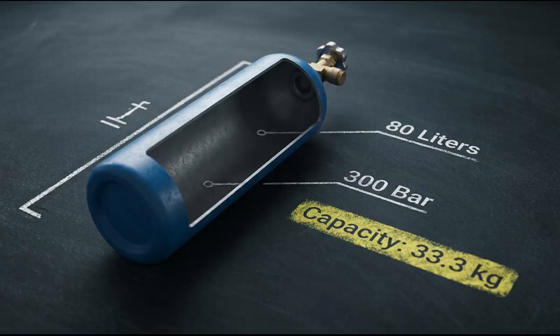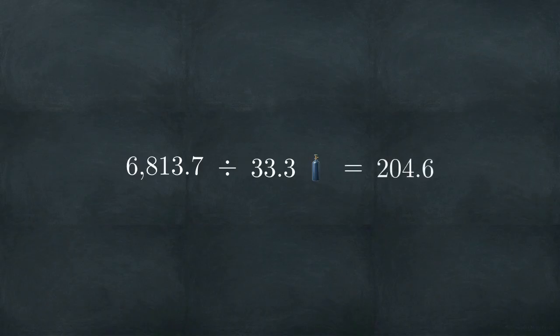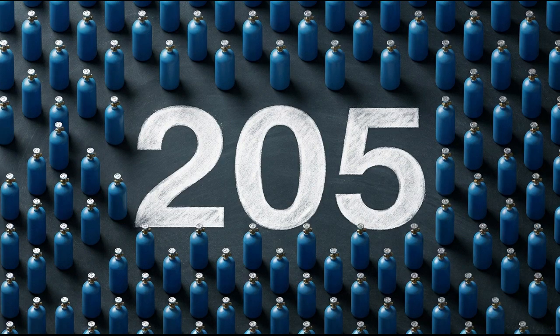cylinders. Using standard 80-liter cylinders pressurized to 300 bar, each unit holds 33.3 kilograms of IG-541. Dividing 6,813.7 by 33.3 yields 204.6. Since we cannot install a fraction of a cylinder, we round upward, requiring a duty bank of exactly 205 operating